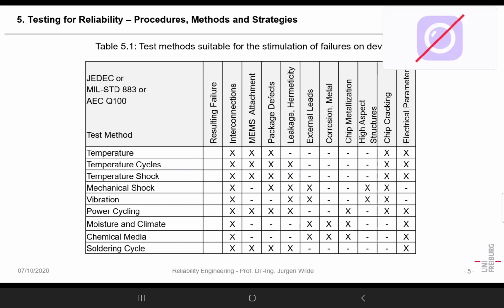So when we soldered the board and it was not working, then analysis found out we had a device which was defective, and in that way we must exchange it. So it is soldered out and soldered in again, and sometimes the second soldering is not done by hand, but again in the machinery. So the equipment is typically soldered twice.